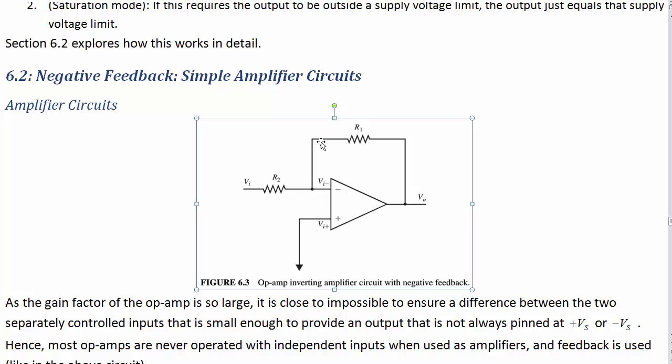So whatever that current is, multiplied by R1, is going to give us a voltage difference from Ohm's law here. So let's make sure we've got the directions right. If the current is going from left to right, and the current is equal to I, then the voltage that would cause that would be 0, the side the current's going in, minus V out.